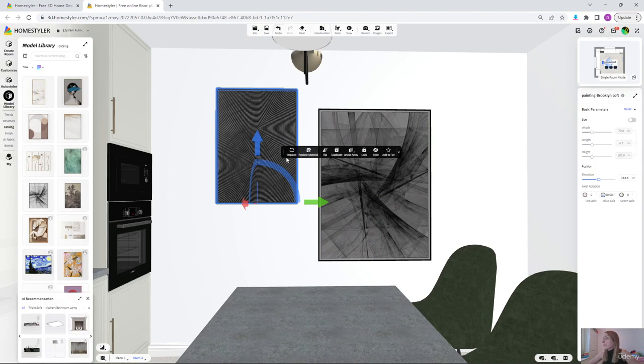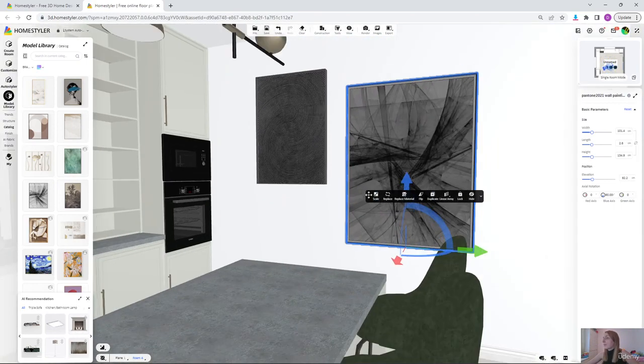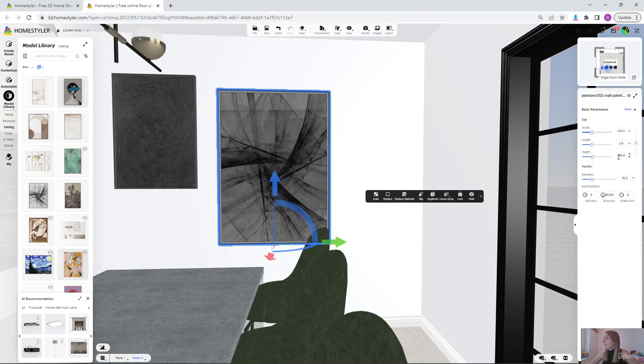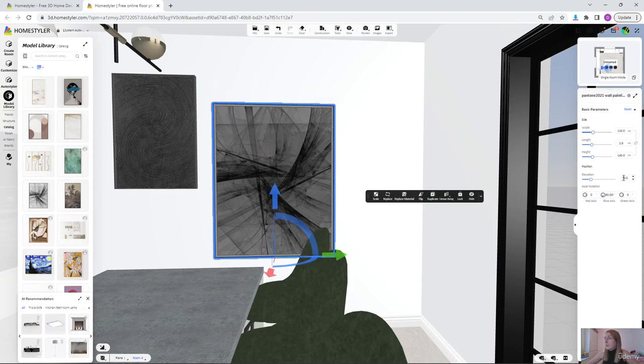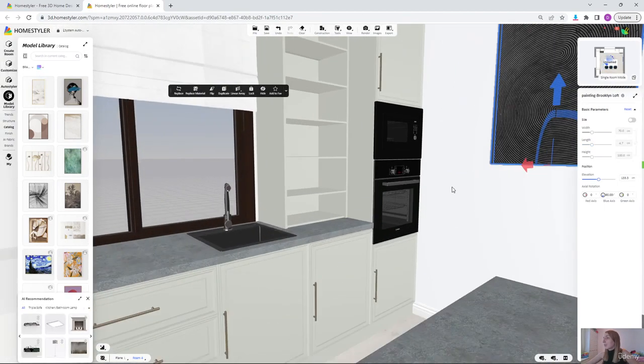When hanging the decor, the paintings, you need to consider its middle line to be at around 140 centimeters. So we have the height of 140 and the width of 110. Okay, so I'm gonna put 70 elevation. And for the other one, I'm gonna center it.